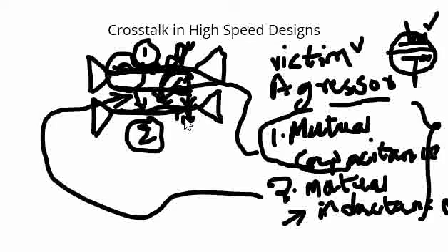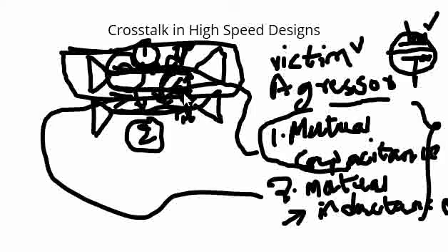Now, one of the biggest challenges we face in PCB designs, especially in high-density boards, is that we cannot increase the spacing as per our convenience, right? The board has densely placed components around, and we have to live with some of the coupling. In these scenarios, ensure that there is a proper ground plane very close to the signal, such that the energy couples more onto the ground than onto the other signal. This is one generic implementation that can be done.